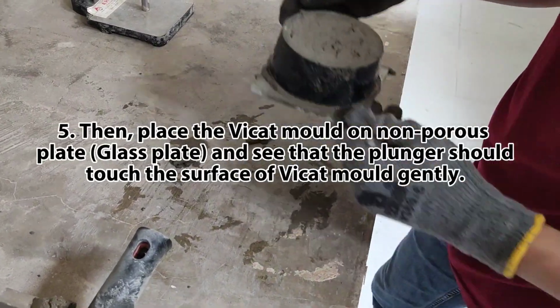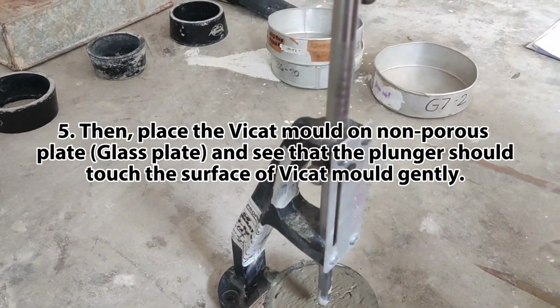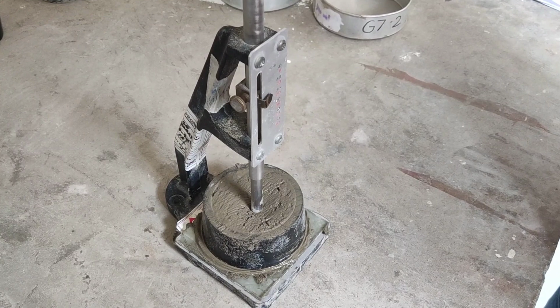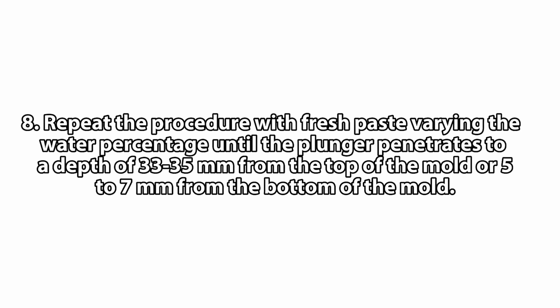Then, place the Vicat mold on a non-porous plate or glass plate and see that the plunger touches the surface of the Vicat mold gently. Sixth, release the plunger and allow it to sink into the test mold. Seventh, determine the penetration 30 seconds after release of the plunger. Lastly, repeat the procedure with fresh paste, varying the water percentage until the plunger penetrates to a depth of 33 to 35 millimeters from the top of the mold or 5 to 7 millimeters from the bottom of the mold.